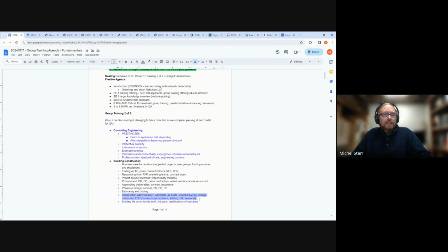Construction administration is the aspect of the building getting built, but before it can be built, there's a lot of paperwork, which is in the form of submittals. So the contractors are looking at what's said to be necessary for the project and working with vendors to find agreeable products or solutions to install, and possibly submitting them if that's what the construction administration process and the front end of the specification says to do.